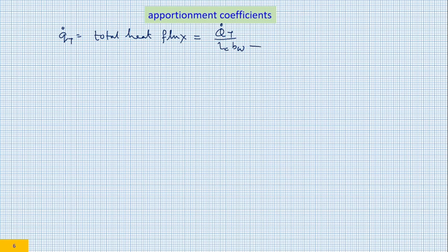What is this LC into BW? This is the contact area in case of flange surface grinding. In other kinds of grinding, whatever would be the expression of contact area, that will come out.